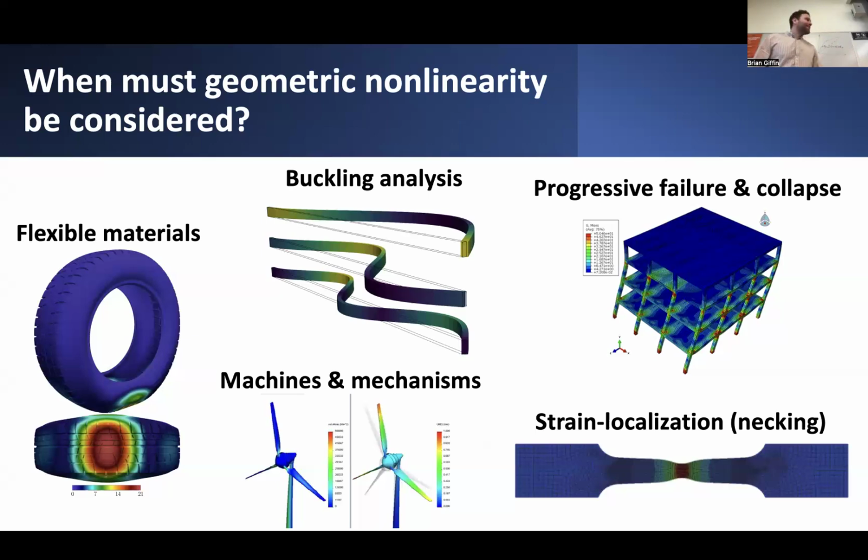Foams, and a bunch of other materials like that are relatively flexible and undergo large deformations. So for those types of materials and analyses that include them, usually it's a good idea to turn on your large deformation effects. Also, because they happen to exhibit somewhat nonlinear elastic behavior, to include that nonlinear elastic behavior, it's also useful to treat it as a form of geometric nonlinearity.